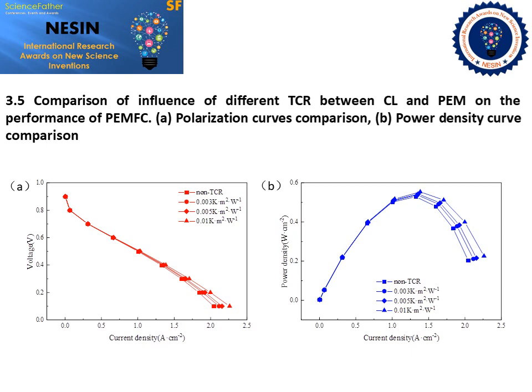And it also shows that it can be considered in the process of membrane electrode fabrication to increase the TCR between the CL and the PEM by reviewing the fabricating process, especially the membrane electrode assembly made by the researchers, not a professional production plan, because the surface of this membrane electrode assembly is more rough and easy to produce large TCR.